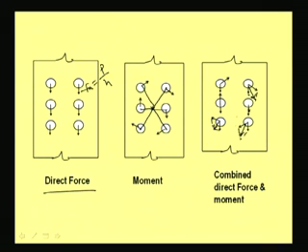From this it is clearly understood that the rivet is going to exert more force in this one and in this one, not in this. These two rivets will not exert more forces. Also this one is just Fa minus Fm, so this is also not going to exert more force. So, these three rivets are critical. Depending upon the magnitude of Fm and the geometrical position of the rivet group, we have to decide whether these rivets or those rivets are exerting more forces. So, we have to calculate and make it.